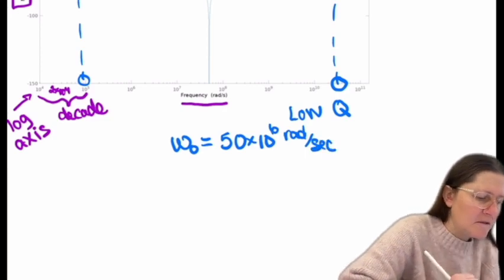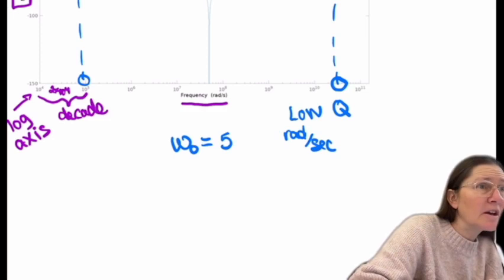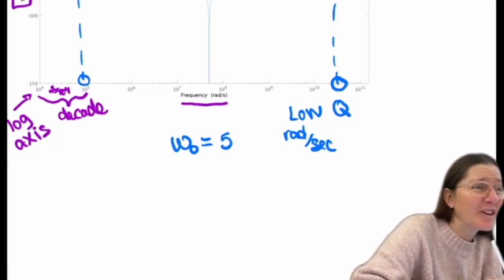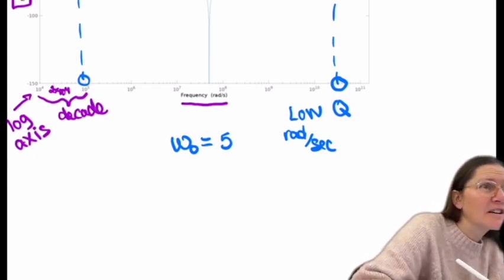You can also do Bode plots. I just learned that right now. You can just do Bode plots on Wolfram. You don't need to put in MATLAB. Oh, really? Yeah. You just type in Bode plot transfer function and search that, and then it pulls up a transfer function block, and then you can just plug in your function to that, and it'll graph it for you.